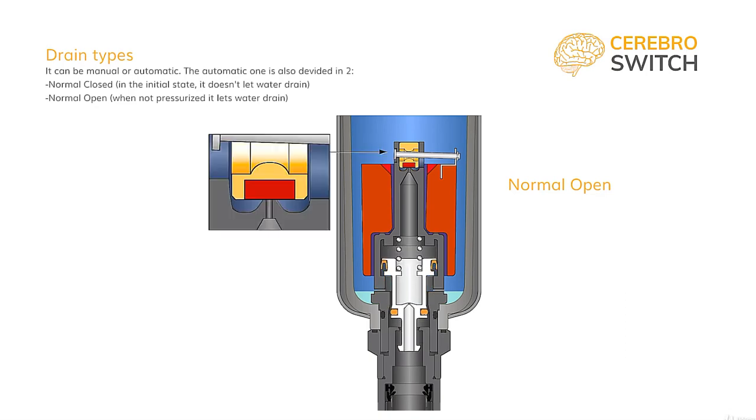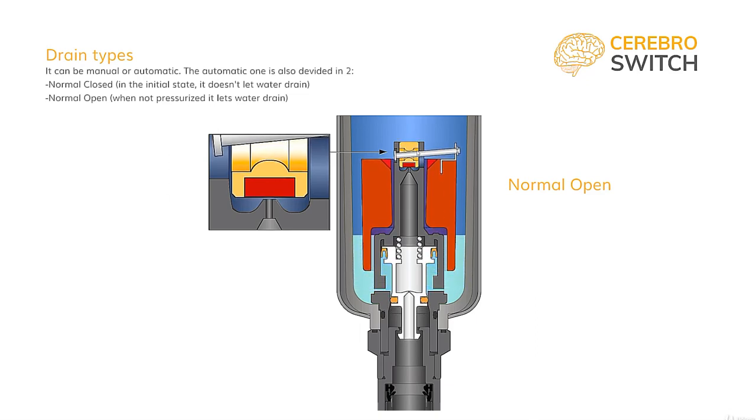As this design requires a certain pressure to operate, the disadvantage with the normal open auto drain is that at the system pressurizing stage, if you use too many of them, the compressor might not keep up with the initial air leakage. But, as discussed before, it will keep our air filter drained at all times, when in use or not. Now, for the symbol.